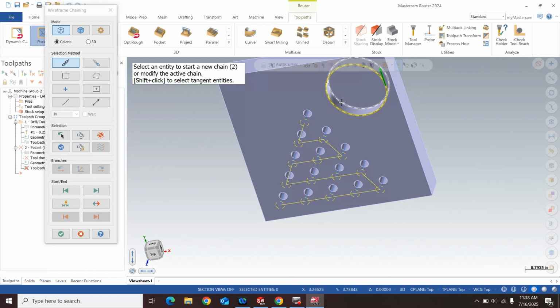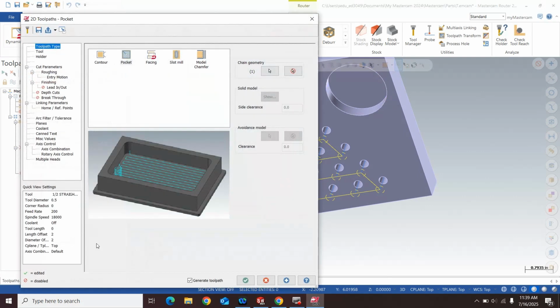Okay, if you select the bottom circle, it's going to cause the bit to drill all the way down through this circle and then try and cut out this 1/2 inch in one go. And if all of your other steps were set up correctly, it would then drill an extra 1/2 inch down into the table, which we don't want. You'll likely break the bit and also ruin your project. So we want to make sure that our green arrow here is going clockwise. Once all of these are set up, we're just going to press OK.